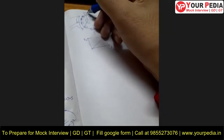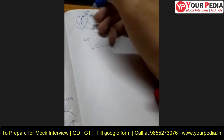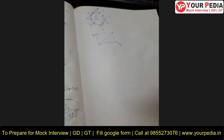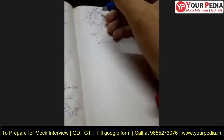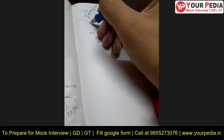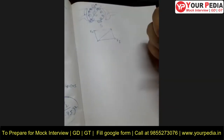If some flux density is present there, currents will flow through the short-circuited coil and damage the brushes. To tackle that problem, we shift the brushes according to the resultant armature flux, such that there's no damage to the brushes.